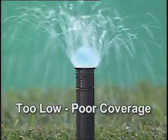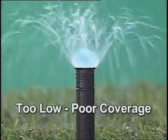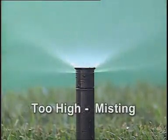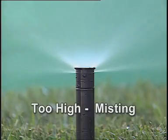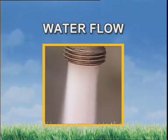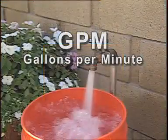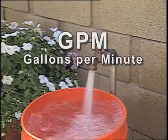If the PSI for your yard is low, fewer sprinklers may efficiently operate at the same time. If the PSI is too high, that also will have an adverse effect on the sprinkler's performance. Another measurement that is critical in the design of your system is the amount of water, or flow, that is available through your supply line. This is measured as gallons per minute, or GPM.